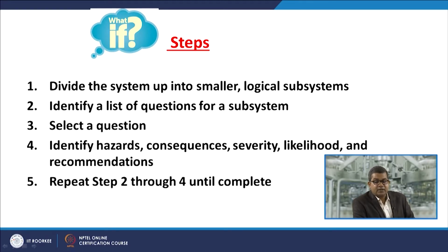You select a question, identify the different types of hazard available, then the consequences, what is the severity, what is the likelihood, that means you need to carry out the probability analysis, and what are your recommendations based on your technical knowledge, technical competency. Now if you are not satisfied with all these things, then you repeat step number 2 to 4 until it completes, or until, as an engineer, you are satisfied with the responses.